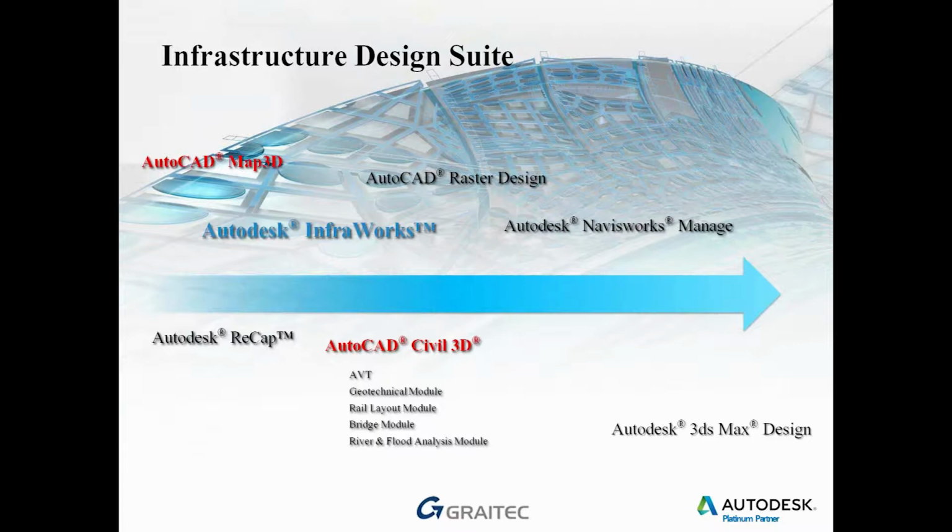So you can bring in your data, do your conceptual stuff, and then put that model straight into your Civil 3D package and do the design. What it's also good at though is at the back end. So once you've done your real design in Civil 3D, you can take that model and sit it straight back into Infraworks, which allows you to share it a lot easier, and it'll do a lot of the visualizations and storyboarding. We're going to do that in the next session, and we'll talk about that later.